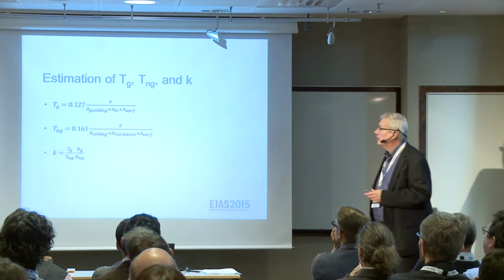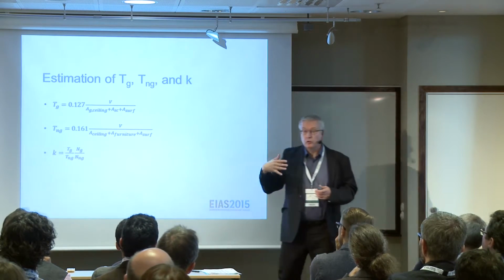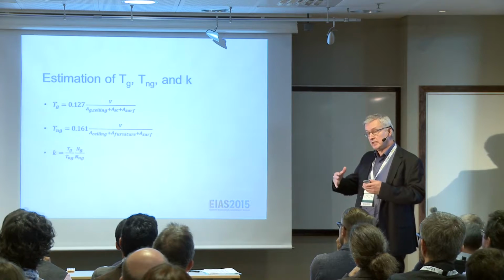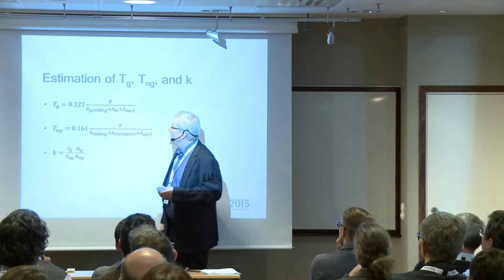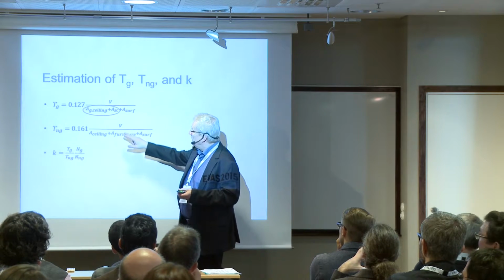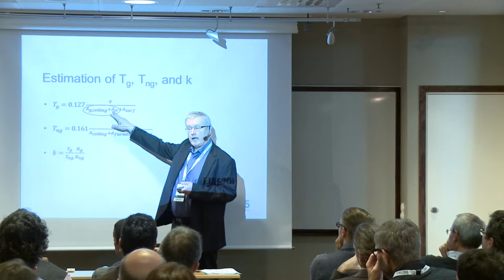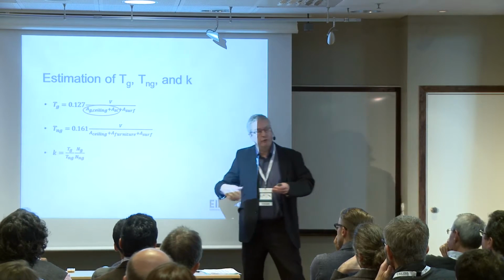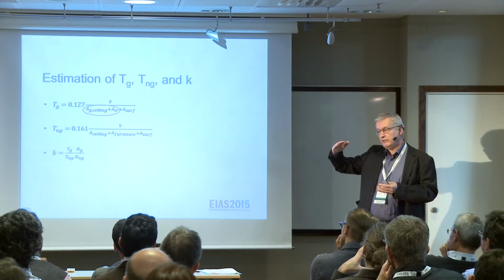And when it comes to the grazing reverberation time, one way is to assume a two-dimensional diffuse sound field. Like Sabine assumes a three-dimensional diffuse sound field, we assume a two-dimensional one. That's why we have another factor here. But the most important thing here is that we can include an equivalent scattering area, because the interpretation of scattering here is that if we put furniture into a room, the main effect will be to, as I showed you, convert energy from the grazing field to the non-grazing.